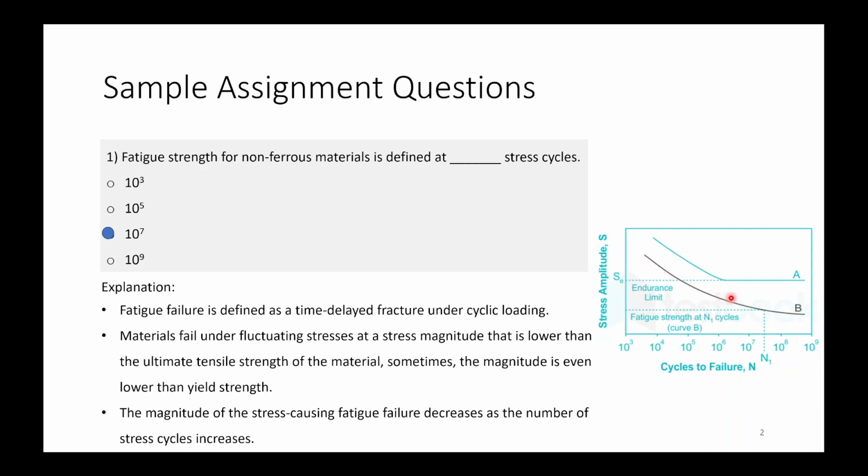So in this case, there is no definite fatigue limit. So you have to define a particular number of cycles. So corresponding to that, you report your stress value. So you keep your stress below that for designing your materials.